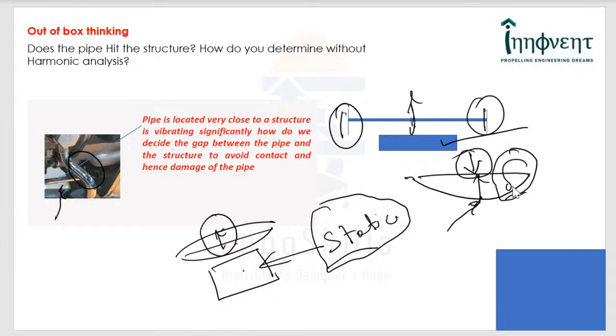But if you deflect the pipe by the equilibrium separation between the pipe and the static structure, say delta, and the pipe has assumed a good amount of plasticity, then obviously the pipe cannot hit the static structure, because once there is plastic deformation, it cannot continue to have that vibratory energy, and therefore the failure is avoided. I mean, this is a very, very simple analysis, right?